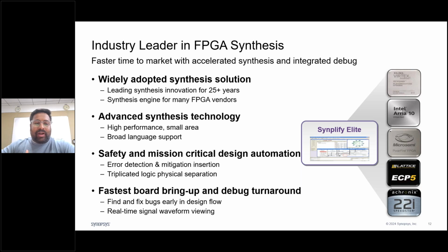What we do is replicate your logic to keep copies separate, and put them into voter logic, so that if any event happens or any of your design gets corrupted, the voter logic takes the majority of 3 and you get the corrected result. It also supports safe-case FSMs. That means if any unwanted state comes, the tool will try to bring your design back to the reset state.